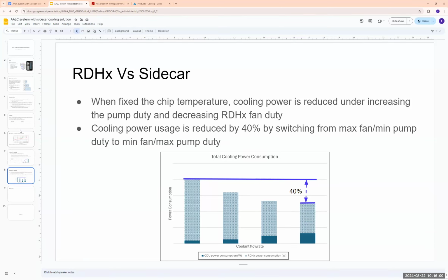But the sidecar is only cooling the liquid, right? With fans. But in a CDU, on the primary side you also have a free cooling system with fans. But you are not considering this part in the power consumption, and therefore the power consumption of the CDU is, I don't know, 10% of the consumption of the rear door heat exchanger or the sidecar, I think.